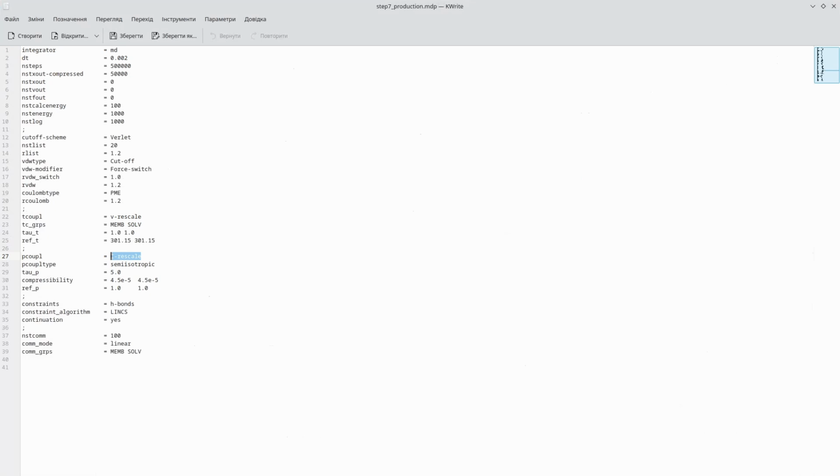Another thing you may notice by observing your equilibration files is that at early stages of equilibration, CHARMM-GUI often sets your time integrator to a 1 femtosecond step instead of 2 femtosecond, which is normal for CHARMM36. That's because it wants to capture even the slightest vibrations of bonds in your system at the beginning, and later you switch to a 2 femtosecond step. But don't be surprised if the early stages take twice as much time for the same trajectory interval as later stages.